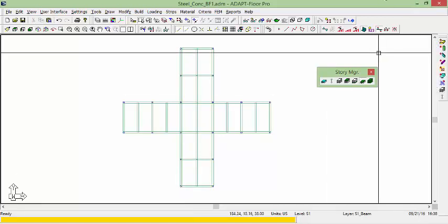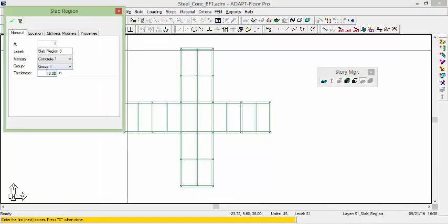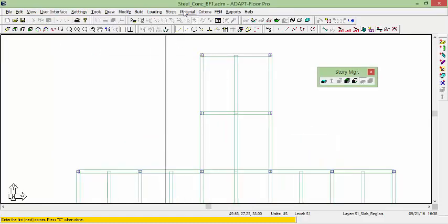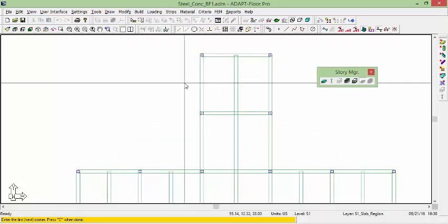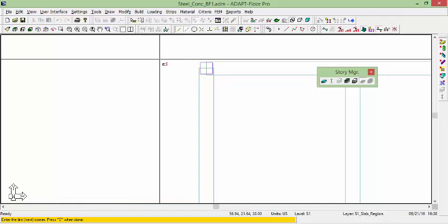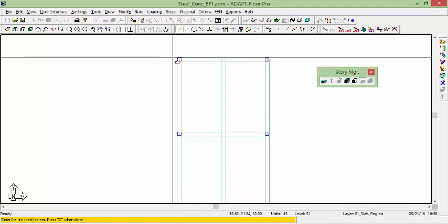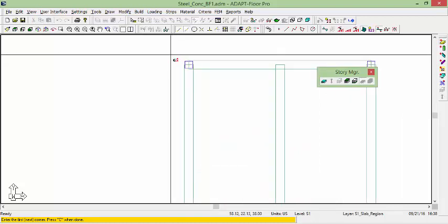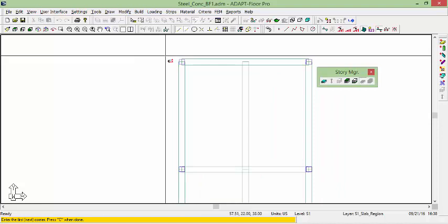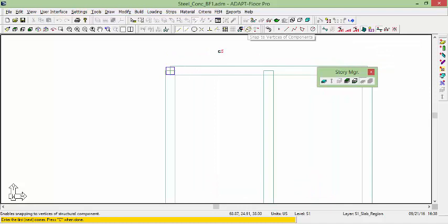So we're going to use what's called a dummy slab in this case. And for the dummy slab, I'll just say that it is 4 inches thick. And under the materials pull-down menu, we could go in and establish concrete material assignments for the dummy slab. The only reason I'm adding it is, number one, to account for the self-weight of the steel structure's infill metal deck and concrete slab, and also to allow us to have the proper wind forces be applied automatically to the structure. So really just a twofold purpose there.